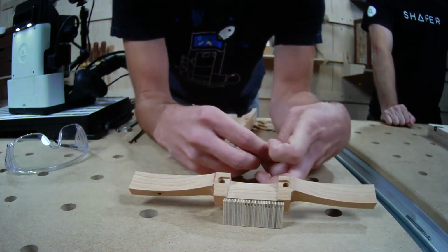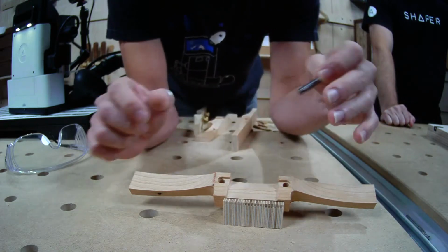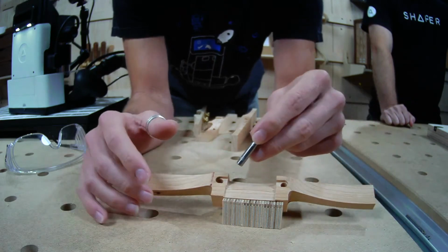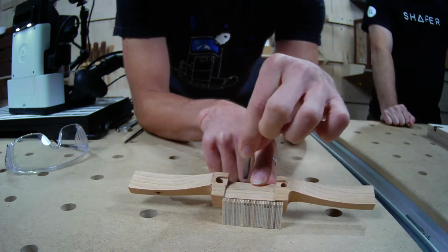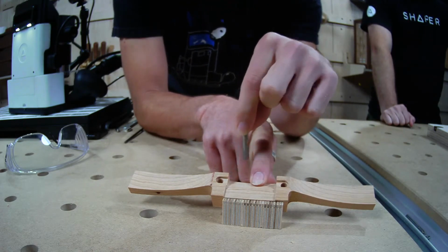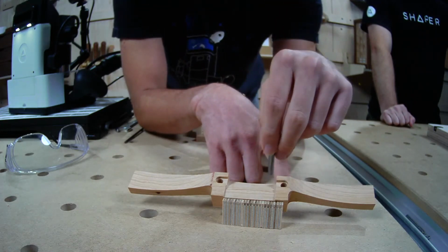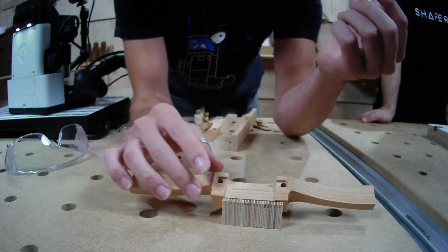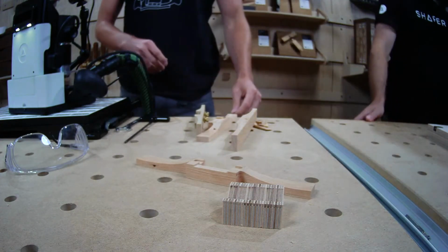We're going to probe off, make a new grid and probe here, here, and here on the block. And we're going to physically align the inner edge of this with the outside of this line here. So now when we probe this, we have a grid that's aligned to this, and we can just make a quick rectangle on tool starting at 0, going all the way up, leaving room for the back of the aluminum board so you don't cut through it, and you can just pocket these down to the perfect angle, put your piece on, and then you have a perfectly aligned piece that's pocketed out with Origin.